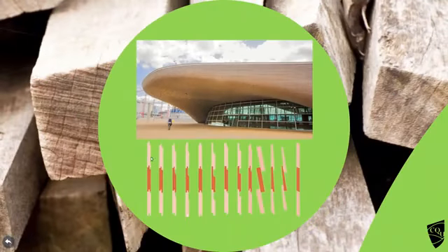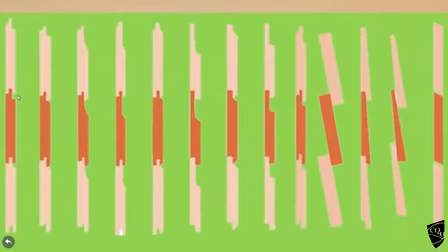And when we're looking at cladding, these are the different patterns you can have of cladding here. So they're all the flat ones. Generally, if you just get them, there's a little nib. That helps, doesn't it? This is a water break, so when the water runs down the outside, it doesn't soak in, it drips over these bits. See, you've got a water break there, another one there, another one there, a little nib there. That one doesn't work as well. And then you can end up with shiplap. They work really well, and that's not too good at all. I wouldn't bother using that because that could bring water in. I know it's sloping to the outside, but it still could allow some water to penetrate there.